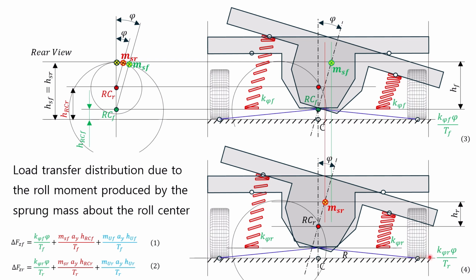As the load transfer increases, the normal load acting on the tire increases. As seen in the previous video, as the normal load on the tire increases, the coefficient of friction decreases, so the external force that the tire can withstand in the horizontal direction increases by a smaller amount than the increase in normal load. Accordingly, when the speed increases during a same radius turn and the lateral force increases, sliding occurs first on the side with greater load transfer.